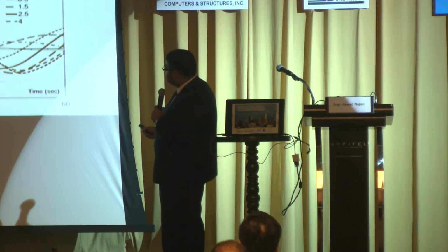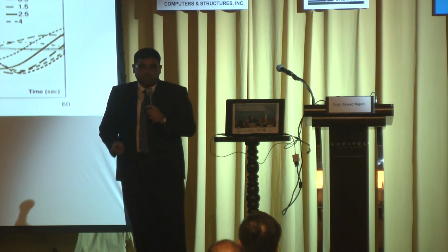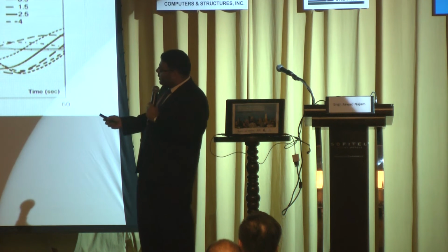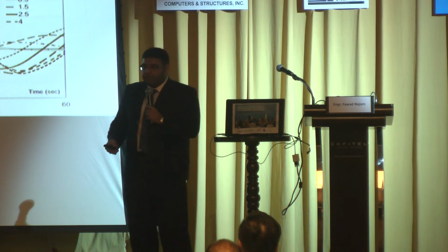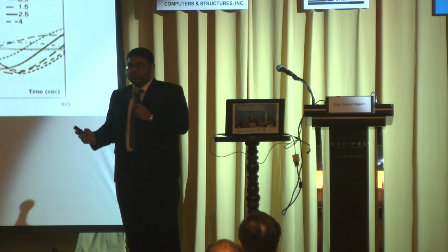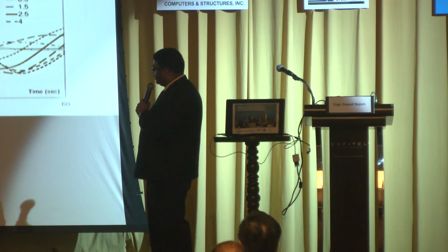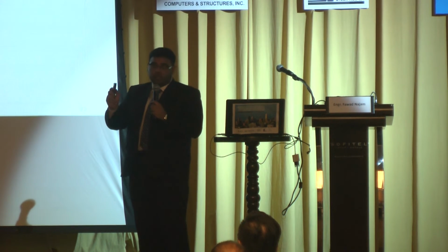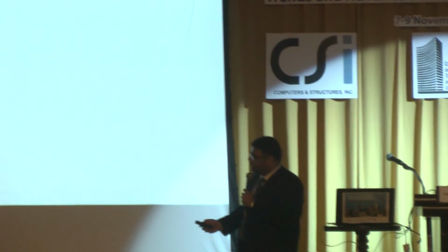And as I am increasing the scale factor, the amplitude is increasing, but at the same time the period is also increasing. So this also gives us a clue: why not we just increase the time period for a single degree and then check whether it is matching with the corresponding nonlinear system or not. So this is the basis of that conversion of a nonlinear single degree into an equivalent linear single degree.